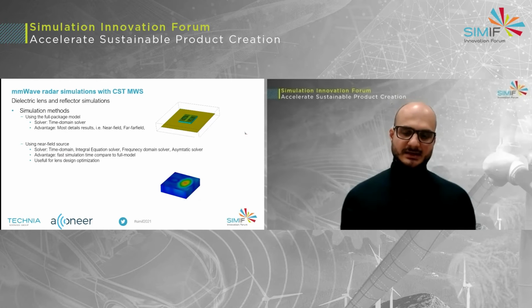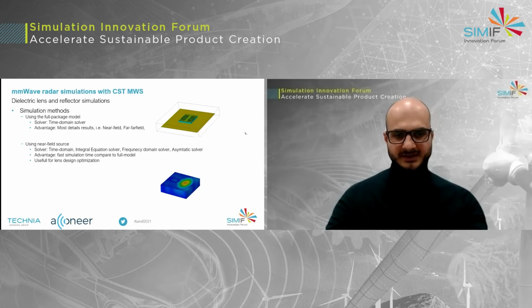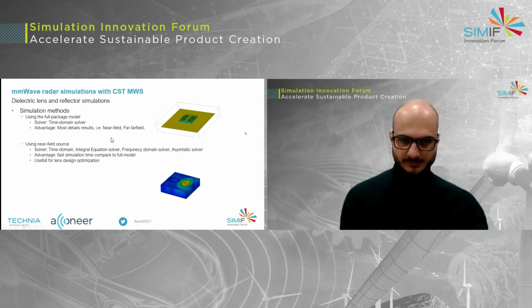So for designing dielectric lenses, one can use different simulation methods. We can split that into two different approaches. One is using a full package model, where we have the full package, and we use that to excite the dielectric lens. And usually we go for a time domain solver in this case.